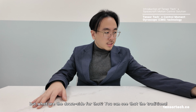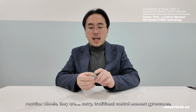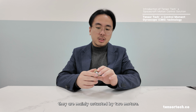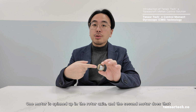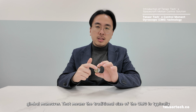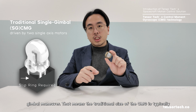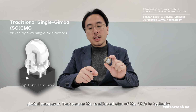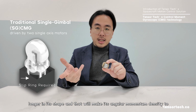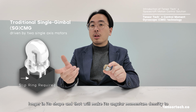You can see that traditional reaction wheels and traditional control moment gyroscopes are mainly actuated by two motors. One motor spins up the inner rotor axis, and the second motor does the gimbal maneuver. That means the traditional size of these CMGs is typically longer in shape, and that makes its angular momentum density lower.